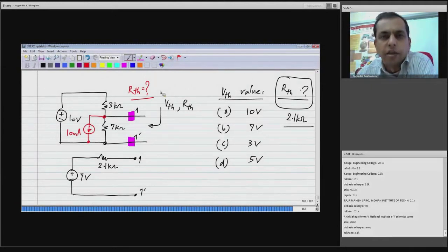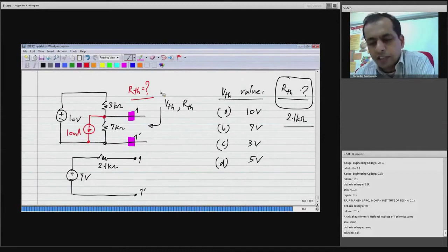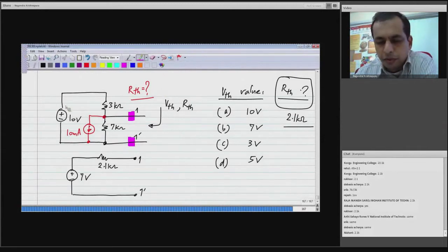Again, as many of you are able to recognize, it's exactly the same, because when you null the voltage and the current source, you short circuit this and you open circuit the current source, you are left with exactly what you had before. So the value of RTH doesn't change at all.